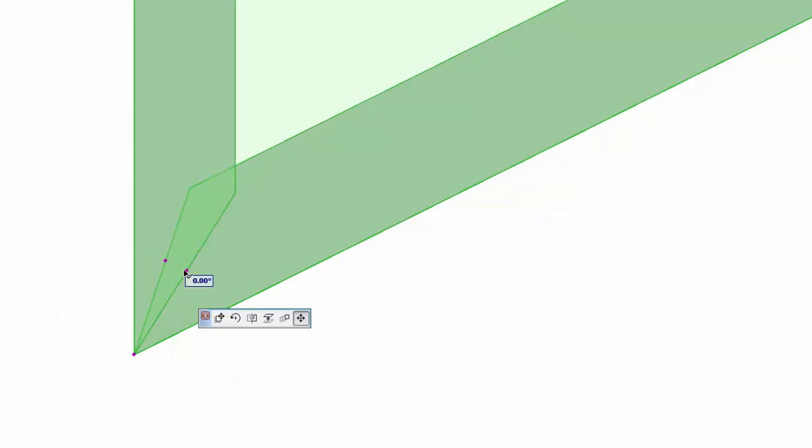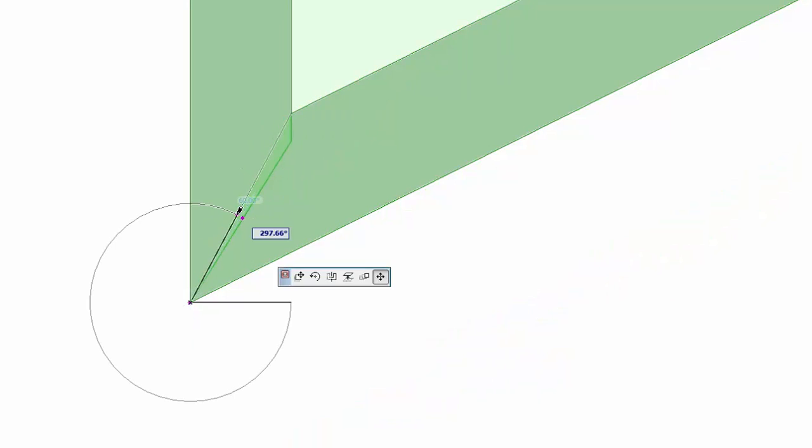I don't know if you can see that faint line that's appearing, but I am snapping to a bisector line there. So I'll do that, and you can see you don't get a clean intersection. You basically need to do it by eye. You could draw some guides for yourself if you wanted to get it spot on, but this is going to get you to within 1/10 of a millimeter accuracy anyway. It's probably something you're not going to see.